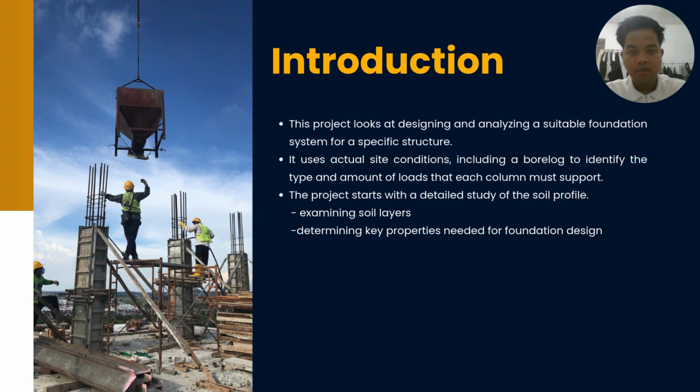Okay, I will explain the introduction. This project is about designing and analyzing several foundation systems for a specific structure, either shallow foundation or deep foundation. For the actual site, from the borehole and load data, we identify the type and amount of load that each column carries. The project starts with detailing, where we examine the soil layers and determine the key properties needed for the foundation design.